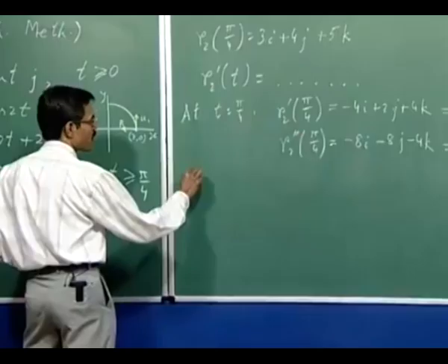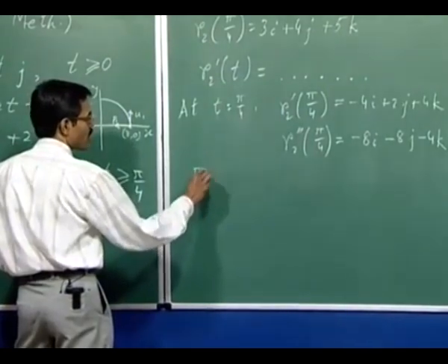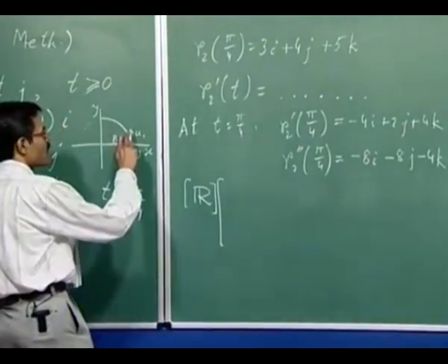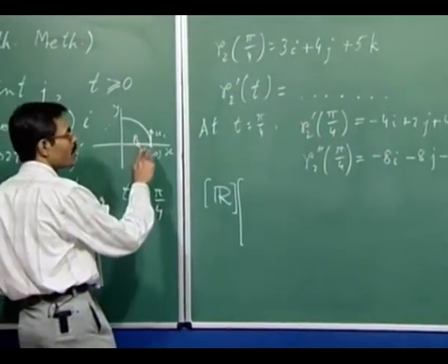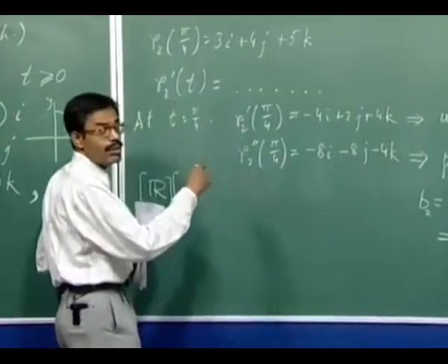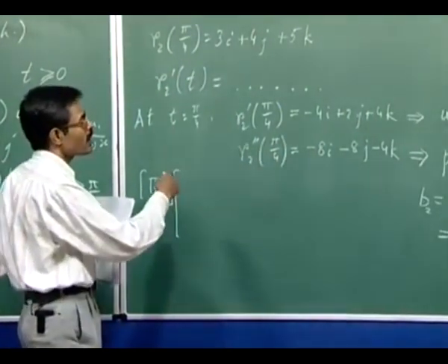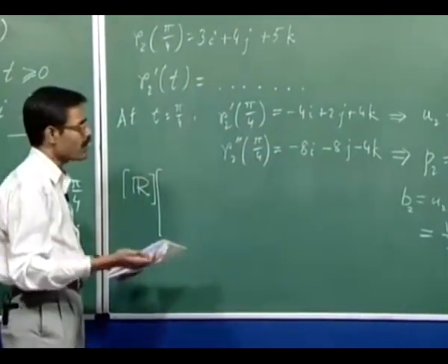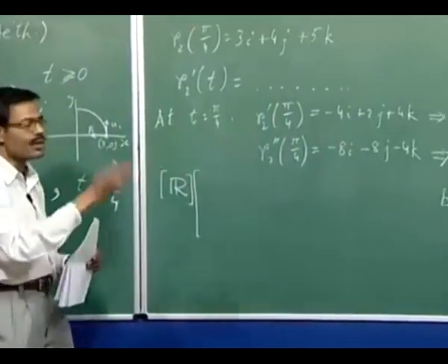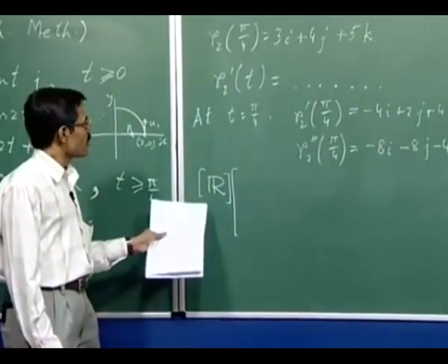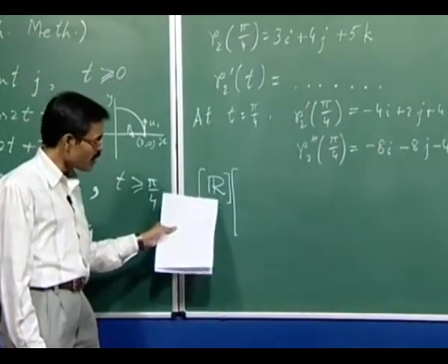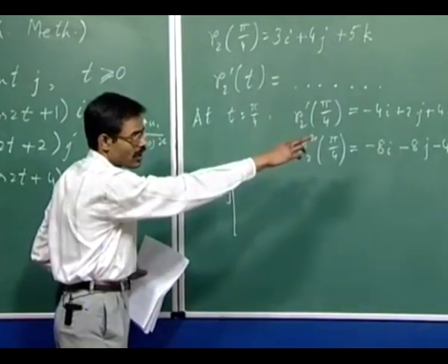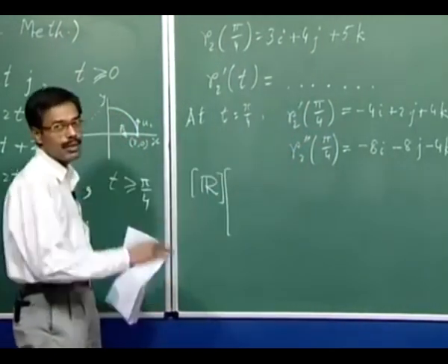So, suppose that the 3 by 3 rotation matrix is R. Okay. So, R transforms U1 P1 B1 to U2 P2 B2. We could do the other way also, that is what rotation would transform U2 P2 B2 to here, but that is not very different because the two rotation matrices are transposes of each other. Okay. So, we are going to do it like this because the matrix that will appear here will be easier to invert. The matrix that would come from there will be more complicated to invert, and we must invert one of the two matrices.